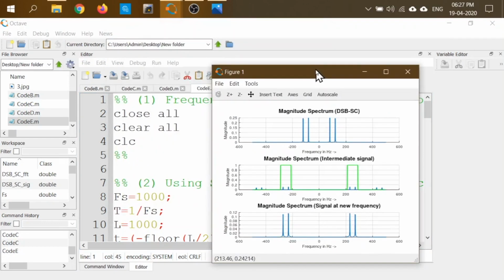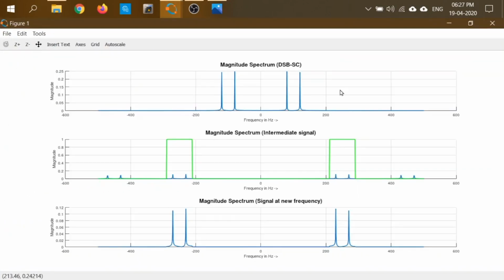So this is the frequency domain result. I have not shown the time domain expressions here, because they are not useful here. So this is your signal, which is a double sideband suppressed carrier signal, and here you have got no carrier, that is why it is suppressed carrier.